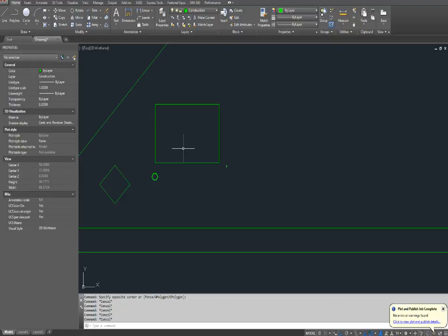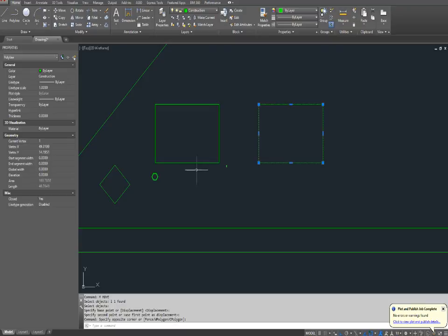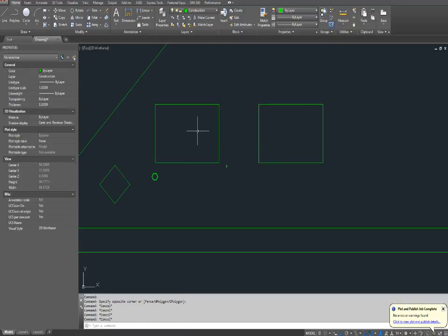I need to create a rectangle out of that. So you could just go in and say rectangle and kind of just pick it and draw it. Okay, now I have a line over a line. So if I move my last created thing, so move, enter, L, enter, you can see that there I have my new polyline that I created as a rectangle, and here's my original 4 lines, right?